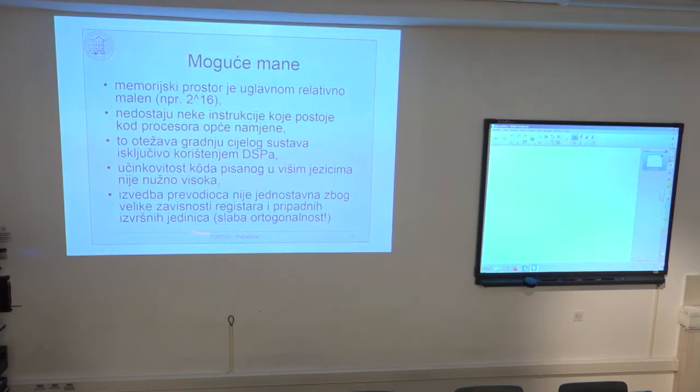Finally, if I want to implement a compiler, it is not an easy task because, as the example showed in the last presentation, you have this non-orthogonality. And that means that, for example, certain input register can be combined only with certain assembly instruction. I cannot, for example, have multiplication directly by taking, for example, shifter input value with some AX0 and directly multiply this in multiplier.